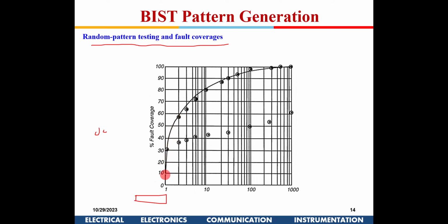And generally in the initial phase you will find this fault coverage. If you generate a large number of random patterns, obviously most of the faults will get covered, but if you see here, if you run 100 random test patterns, more than 95% is getting covered, right? From 100 to 1000 it is again 10 times, right? So you might want to stop at 100 and cover almost 95%, and then from here to here you can either leave this,